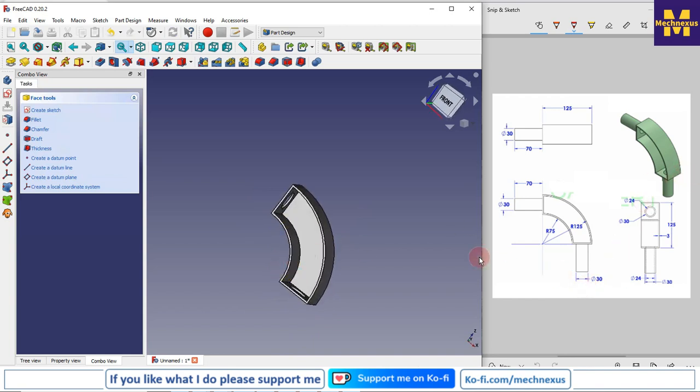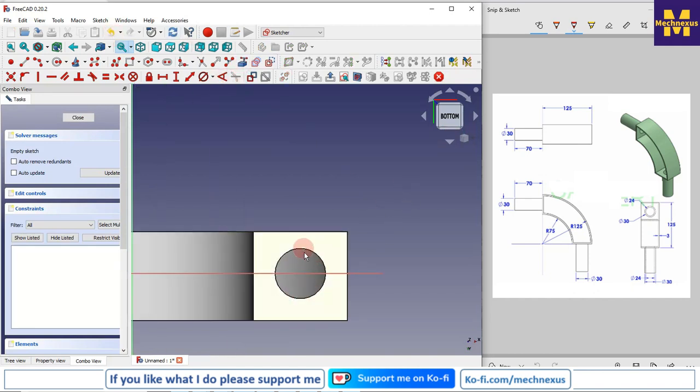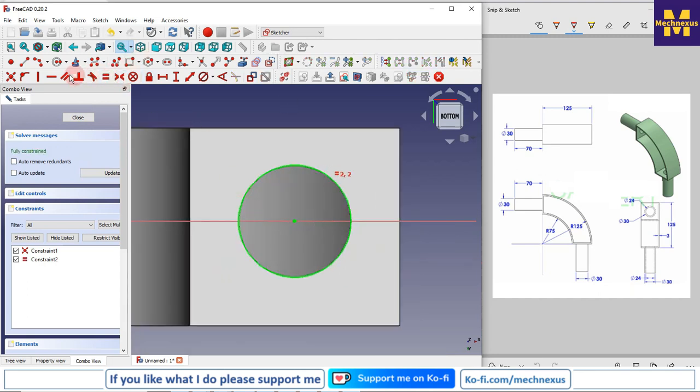Now in our image we can see here the cut, and now I will create a pipe. Pipe is 30 but it should be hollow, so I will select this face and I will create a sketch, and I will project my circle, and I will create a circle, and I will make this and this equal, and then I draw the thickness.